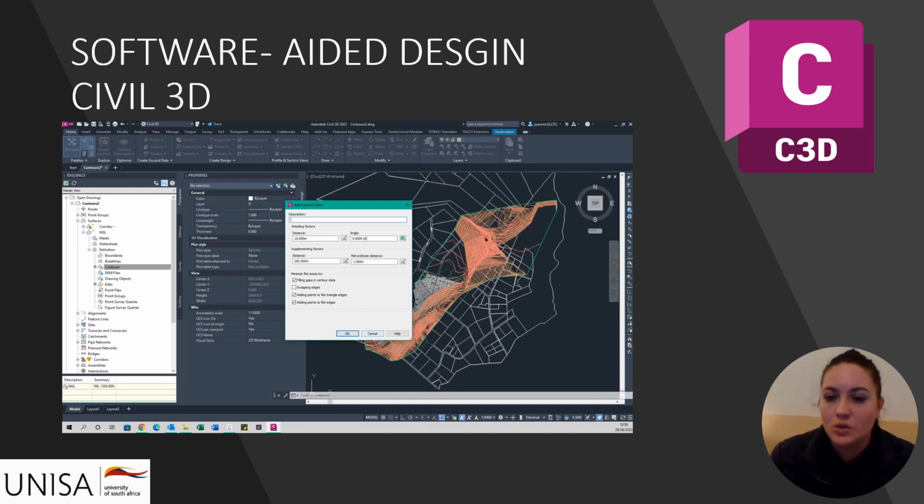I used the provided contours to create a surface in the program, naming it the Natural Ground Level, or NGL. This surface was then used to create a contour base map or TIN surface, which can then create a visual representation of the natural ground level. After this, I created an alignment from the center of the road, starting at the points near the farmlands and ending at the point in the Lion Pride Estate. This gives a 3.3 kilometer road.